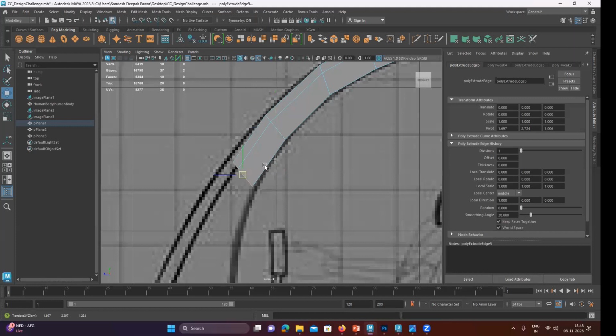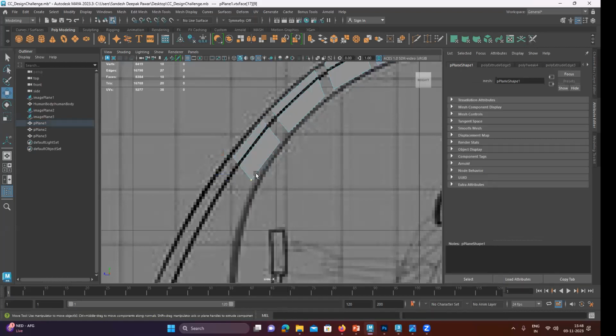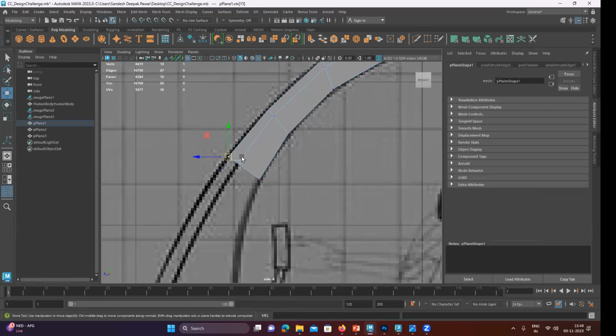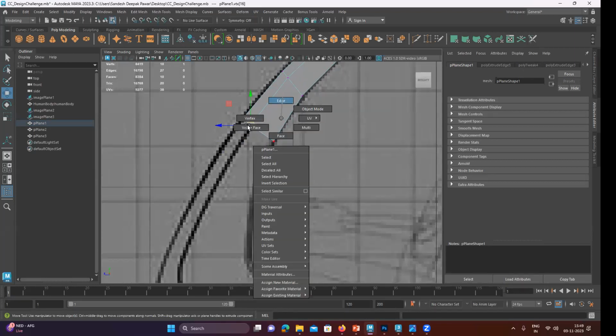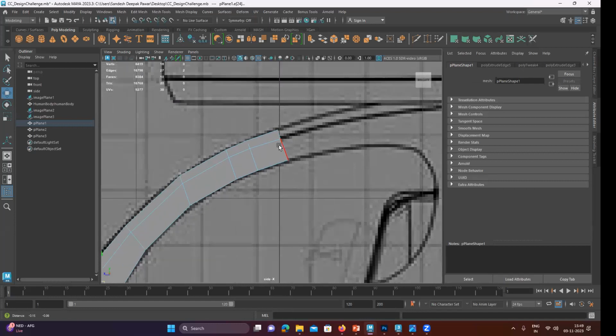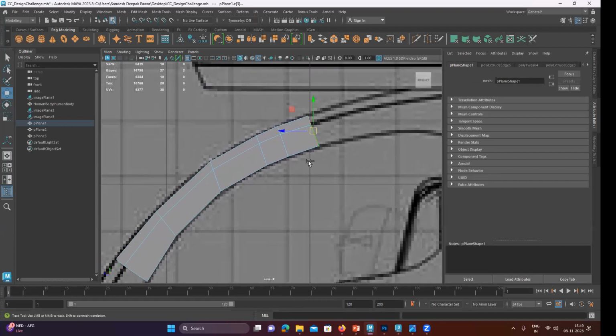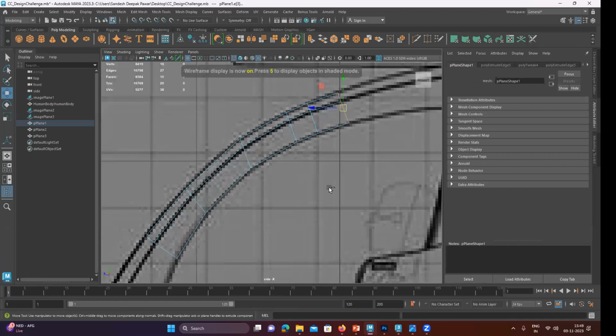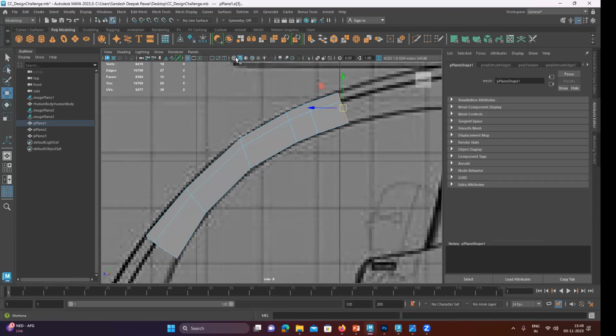Yeah. So again, here I have to scale it, or maybe don't scale this. Maybe you can move the vertices as well. So this is called the edge extrusion method. Once you want to see what is happening, I have to press 4 again and again. So 4 is for wireframe, 5 again for shaded. Instead of that, you can utilize the X-ray mode as well.